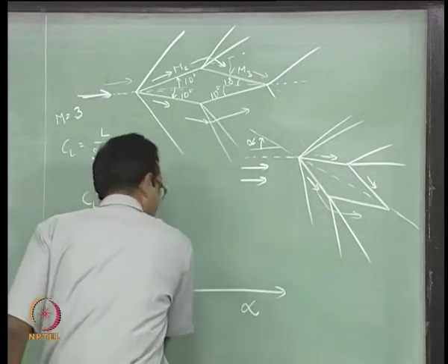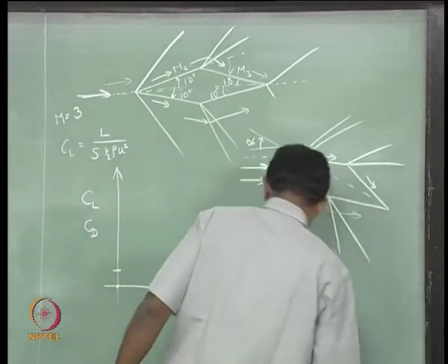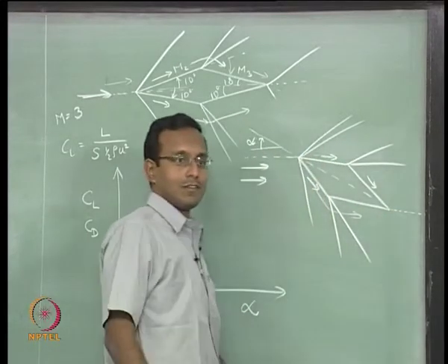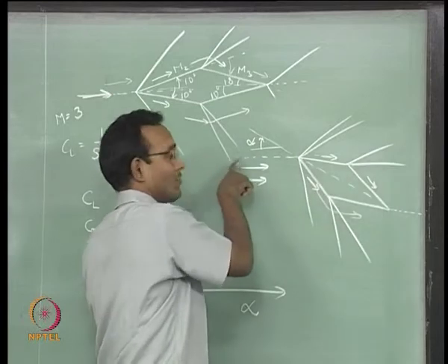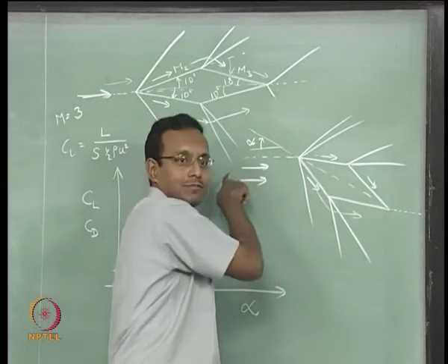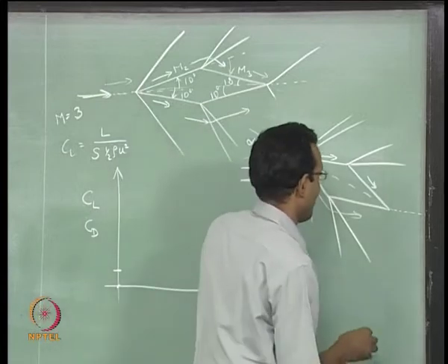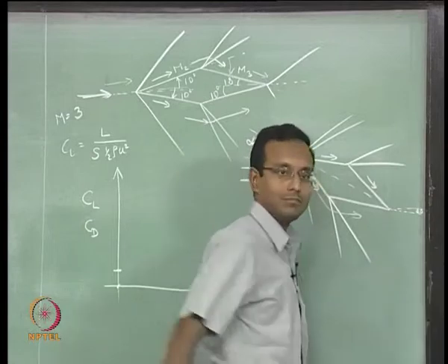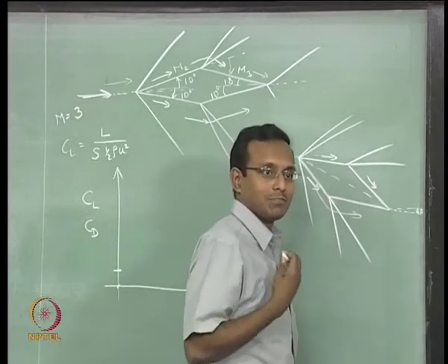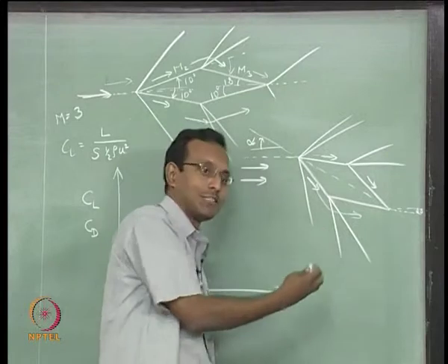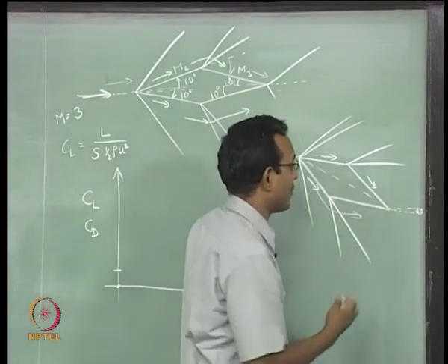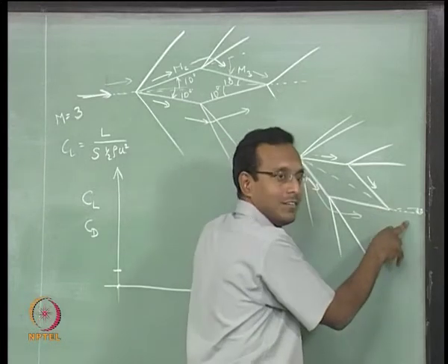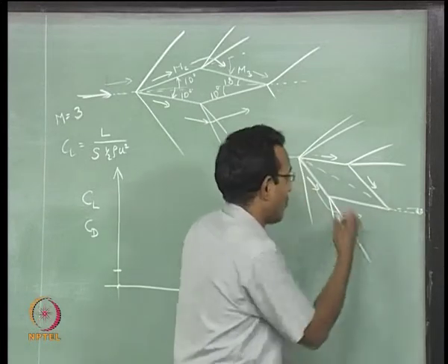So I know that it is roughly going to be close to 0 angle of attack with respect to original flow direction. It will go almost like flow direction when it leaves the airfoil. We will still have that small delta downward. For completeness sake I can call it 0 also, that will force the problem. We do not want to call it 0, let us say we find the angle so that I will match the pressure and match this delta value for both sides.